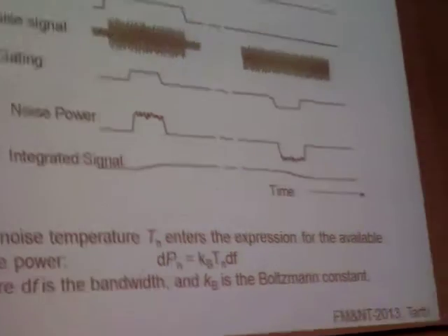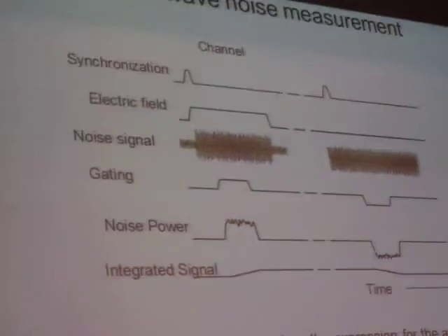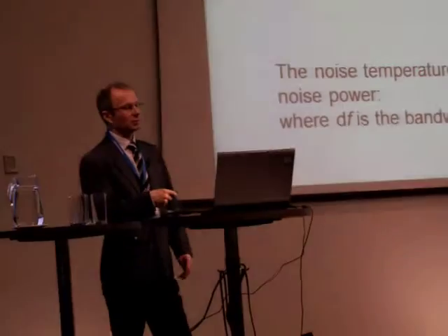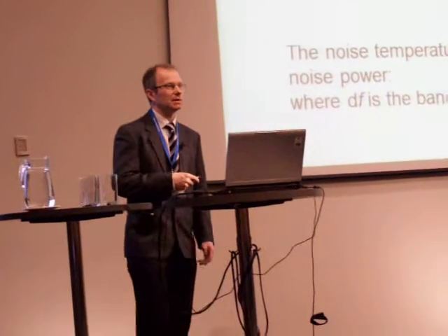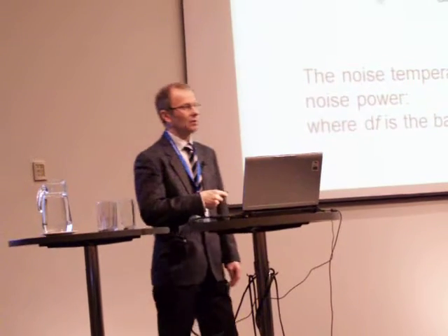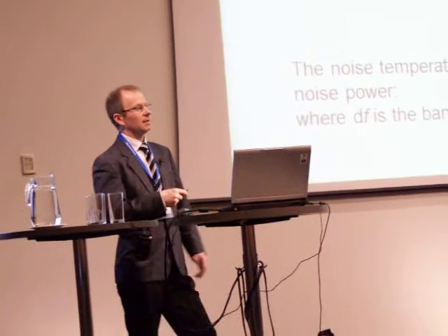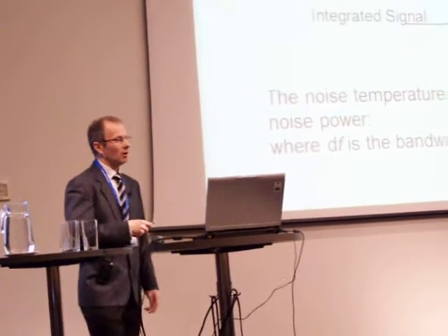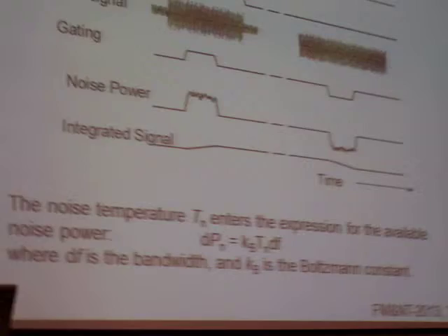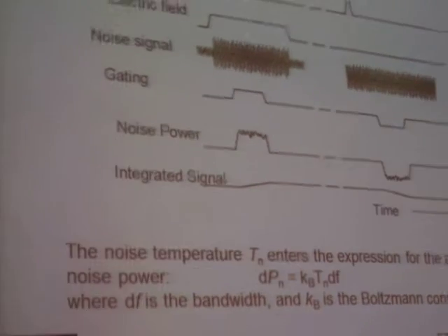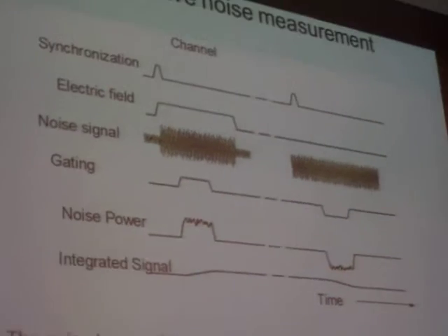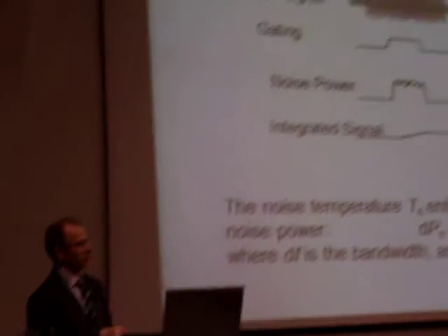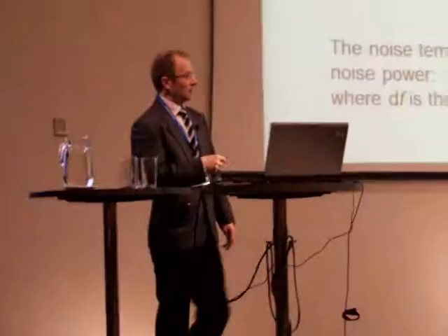This is a scheme of how a noise signal is processed. The application of the two-pulse technique introduces the necessity to measure very weak noise signal, 10 to minus 15 times 10 to minus 12 watts, on the background of the strong voltage up to 10 watts. The circuit used to heat the electrons is decoupled from the circuit measuring electron noise.